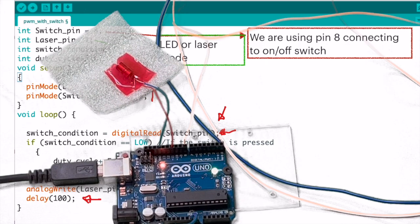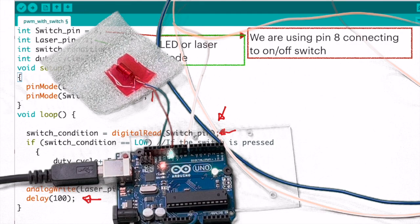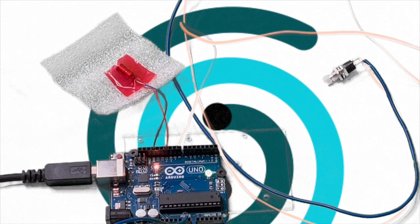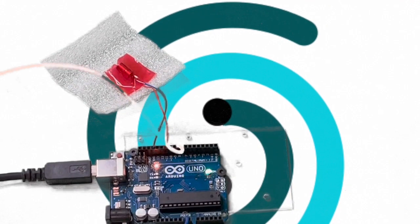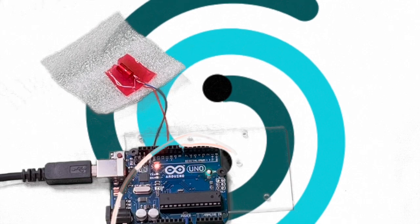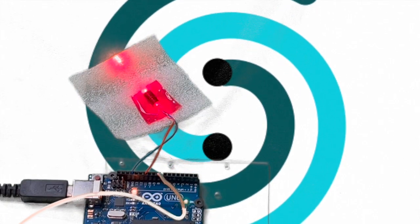This is our setup. We have connected the laser from pin 11 and ground. We also have a push to on switch here connected between pin 8 and ground on this side. I've kept the lead very long so that I'll be operating it from behind, so you will no longer see the push to on switch button. Let us flash the code. See, we have the laser fired up.